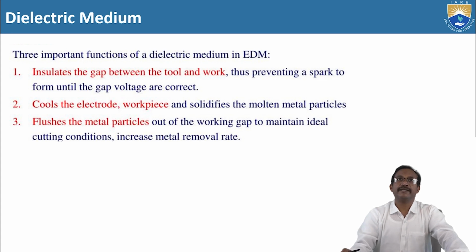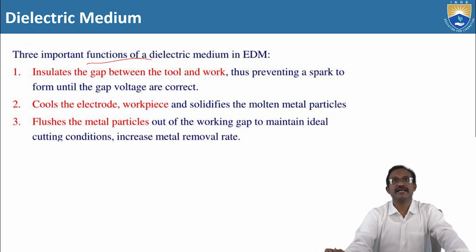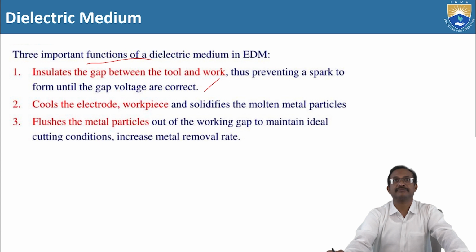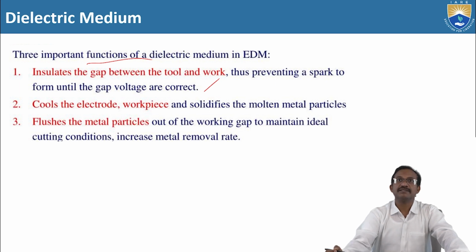Regarding dielectric medium, the following are the important functions of the dielectric medium. First, it insulates the gap between the tool and work, thus preventing a spark from forming until the gap voltage is correct. Second, it cools the electrode and workpiece and solidifies the molten metal particles.